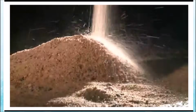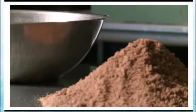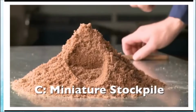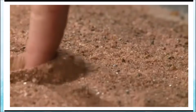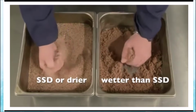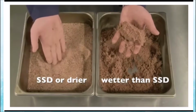For samples that are saturated surface dry or drier, use method A, the mechanical splitter. If your sample is wetter than saturated surface dry, use method B, quartering, or method C, miniature stockpile. If the moisture condition of your sample is not apparent, determine its condition by performing the fragile hand cast. Just squeeze a handful of material. If it retains its shape, assume that it is wetter than saturated surface dry.